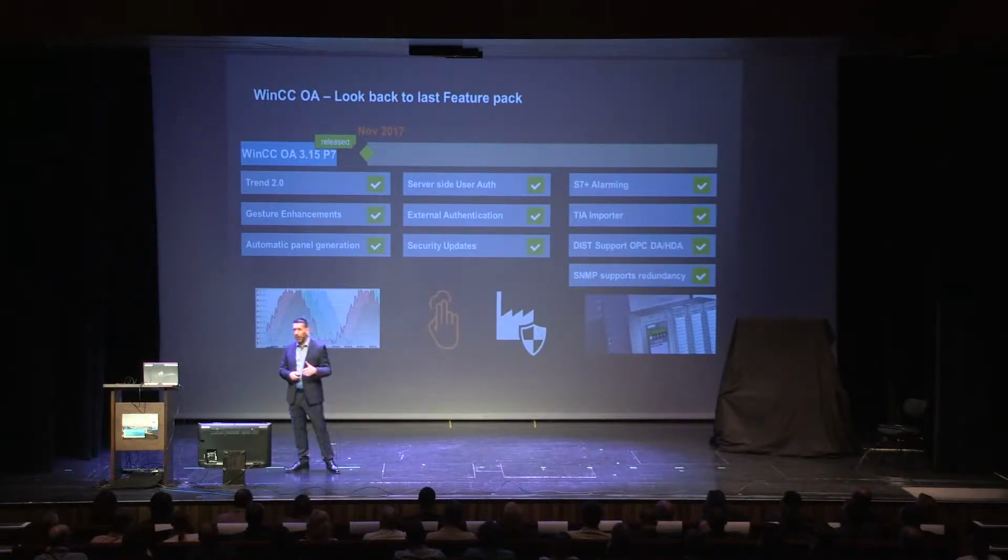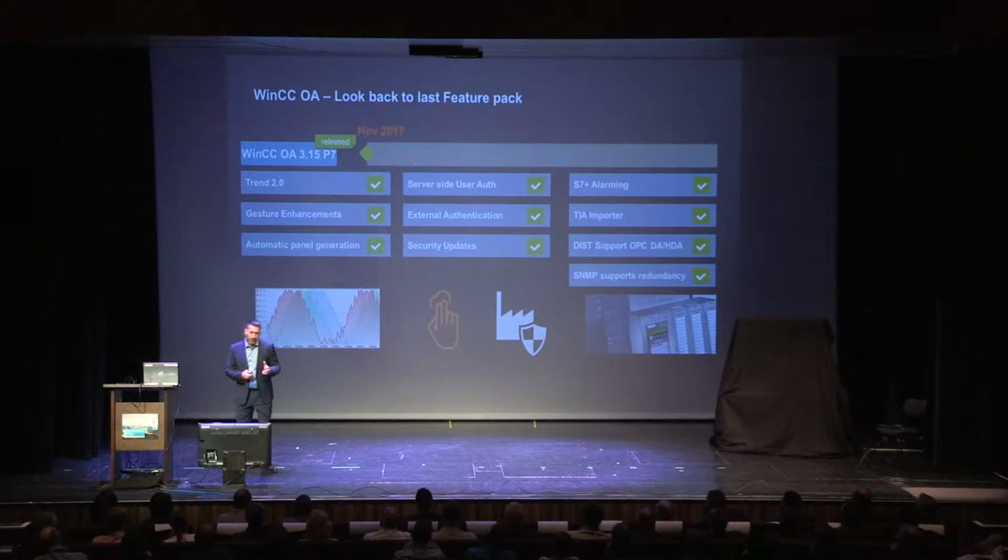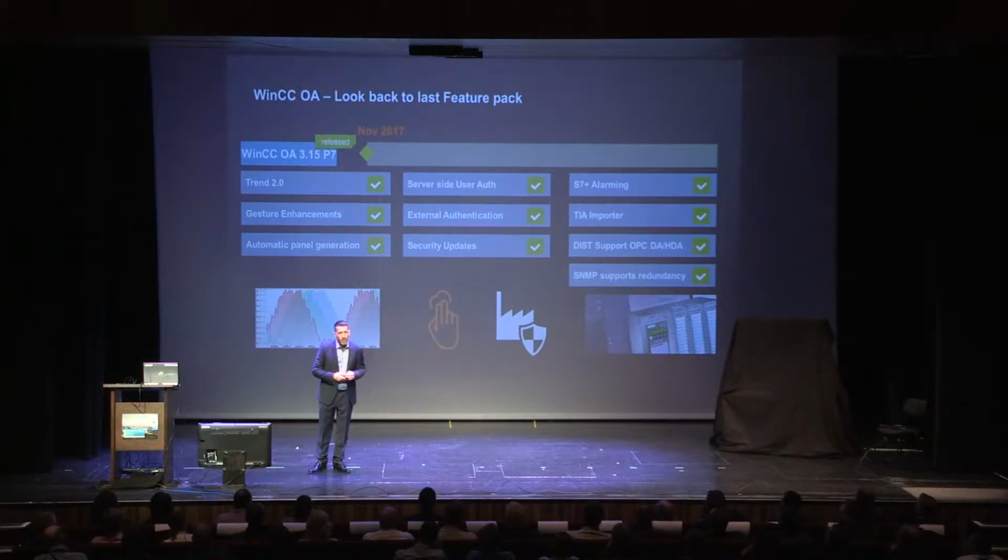So this gives the operator and the user the possibility to visually correlate information about alarms popping up with data, how it is going to change and how it is going to improve. And this is, I personally think, a very important step to support the operator in doing first steps of root cause analytics, because if something happens, it might be very helpful for him to have this direct correlation.